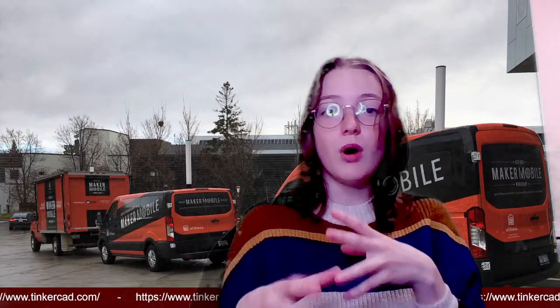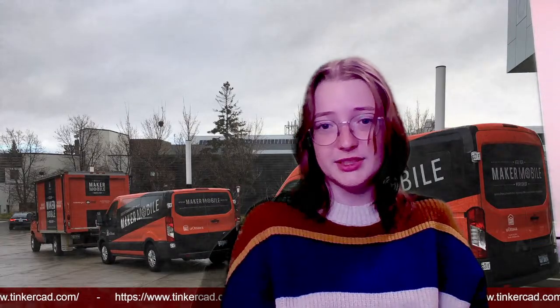A 3D printer will have a type of filament attached to it, which is usually PLA or some kind of plastic, that goes through a nozzle that heats it up really hot. Usually nozzles are around 200 to 300 degrees Celsius, which is a lot warmer than an Ottawa summer day. So it is very warm in there, and it'll melt the plastic coming in through this filament so that it becomes kind of malleable, kind of soft. And we'll be able to put down layer after layer of this plastic to finally create something.